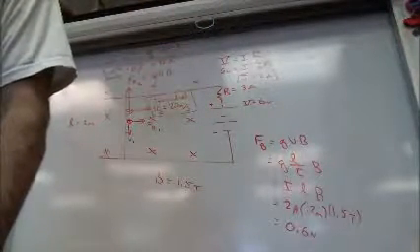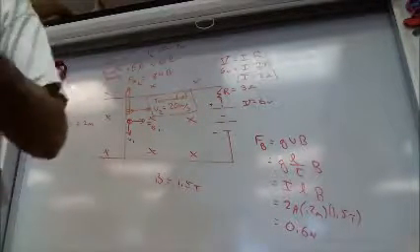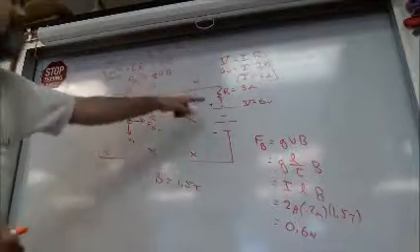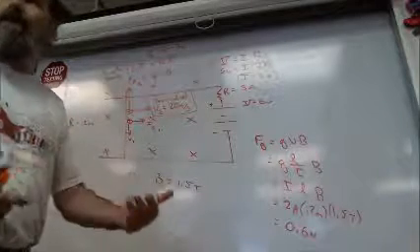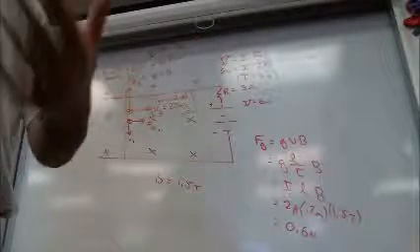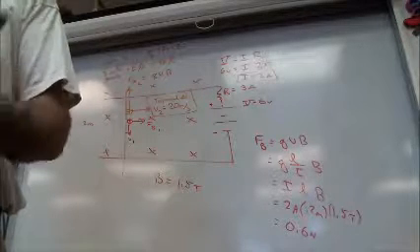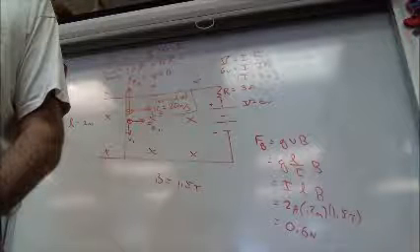Can you picture that? So in a lot of motors, if you prevent them from moving, you're not going to have any back EMF. You're going to get a surge of current. And then that can burn out the motor, because too much current makes for a lot of heat. Even if you have little resistance, you can generate a lot of heat with more current. Did you like that story?